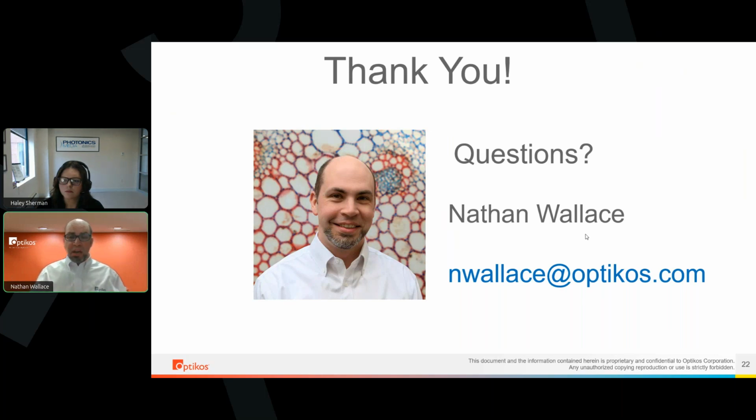Maybe I am trying to compensate for back focal length. Maybe I'm trying to compensate for spherical. Maybe I have a stereo pair and I want to get the magnification just right. So putting in a nominal, doing a measurement, calculating what you need to change and putting that in there. But yes, there are many compensation techniques and mechanisms that you can use for doing airspace compensation.